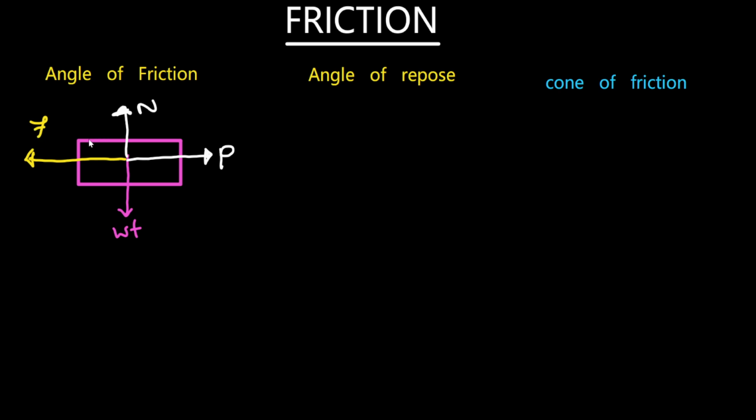This is the F, because you cannot shift a force parallelly; you can only slide it along its line of action, because it's a force. Frictional force I cannot draw over here, so it acts along the contact surface only. This force can be applied at different points: if it is applied here, you will show it here, and if it is applied in between, you will show it there. The point of application depends on the situation, but the friction force will always be applied at the contact area only, because in some situations the block will slide, and in some situations the block will topple.